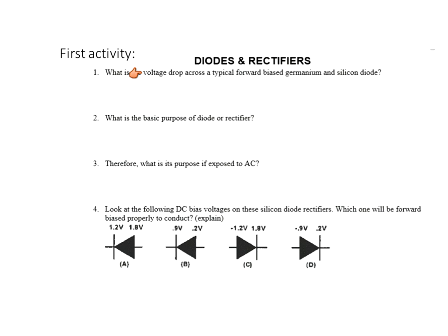Forget about the germanium. It's around 0.5, 0.6, 0.7, or even 0.8, but the second approximation says we always use around 0.7. So the typical voltage drop we will use for estimates is 0.7 volts.